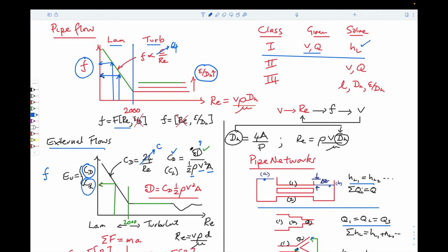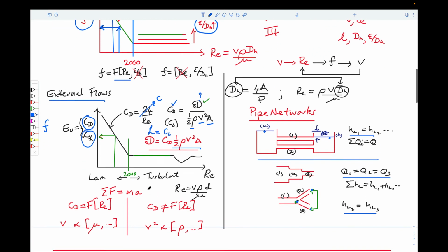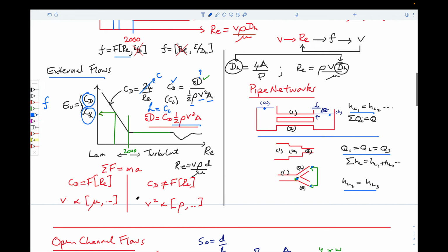So we can rearrange the drag coefficient into this. If it was a lift coefficient, then it would just be a coefficient of lift, and these same terms added onto it. And if, for instance, we know what the coefficient of lift is, the density of the fluid, the velocity, and the area of our system, then we can calculate the magnitude of lift applied to the component.